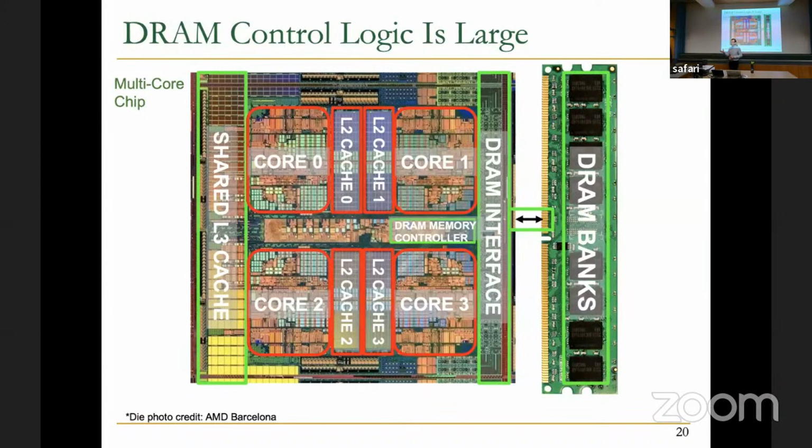Again, it had very nice latency plus cost capacity characteristics. It was much better than hard disks. It was worse than DRAM, but not as bad as hard disks. So it could actually fill a space that's between DRAM and hard disks. So there was a huge gap between DRAM and hard disks. Nanosecond level versus millisecond level. Flash memory was able to get in there with microsecond level latencies. And as a result, I believe it has revolutionized what we have built. Like this, I think, is not possible without flash memory over here. Nobody wants to carry a hard disk inside their pocket, right? Okay. So technology is very interesting.